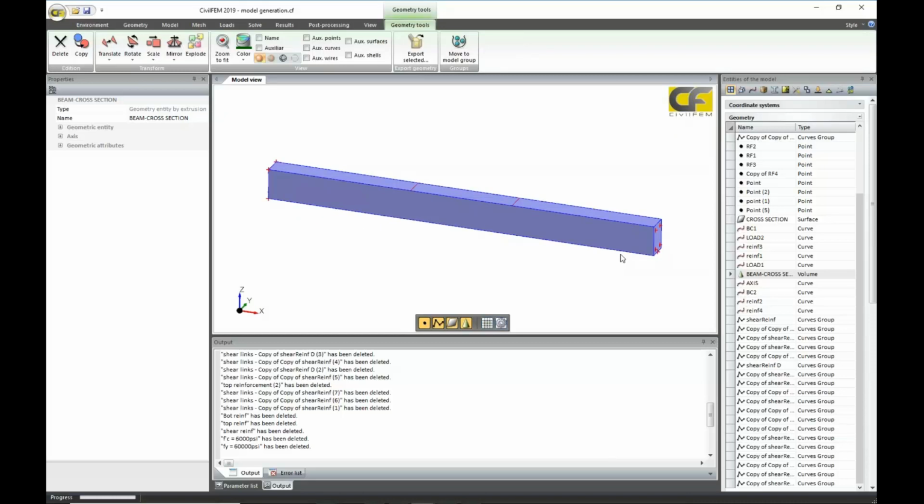Well, we will generate the model with solid elements for concrete, link or truss elements for reinforcement, and we will change different reinforcement configurations for analyzing different possible failures: for compression, for cracking and tension of the reinforcement, shear, or different types of failures.